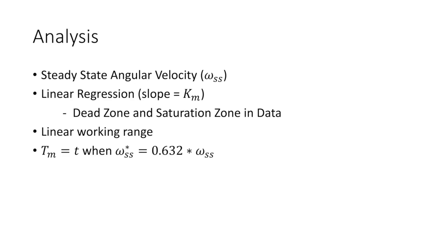So to expound upon the procedure setup, the given quantities are those voltages that are inputted in the system to see the DC motor's response. Flywheel angular velocity and time are all the quantities that are measured during experimentation and outputted from the myRIO microprocessor. The relation between these values is further investigated by plotting angular velocity versus time. This is due to the given equation to figure out omega.